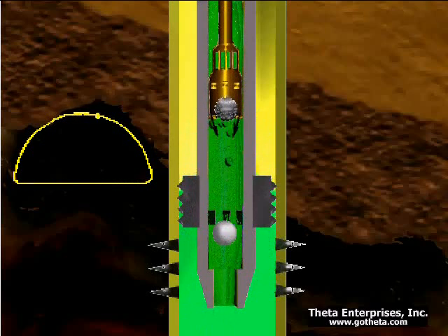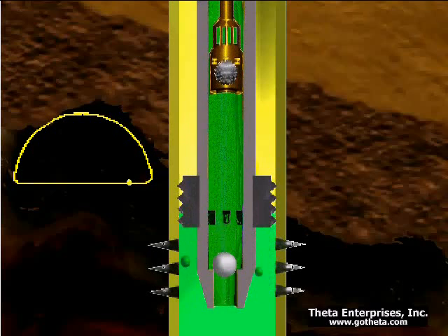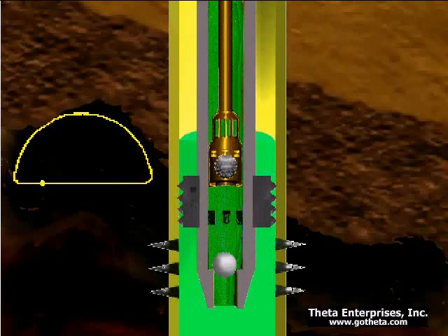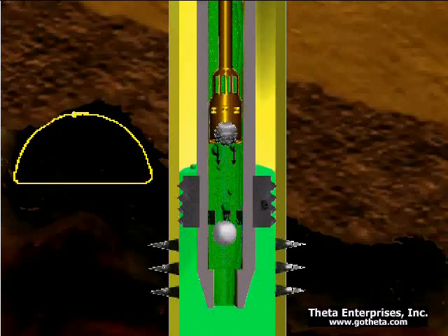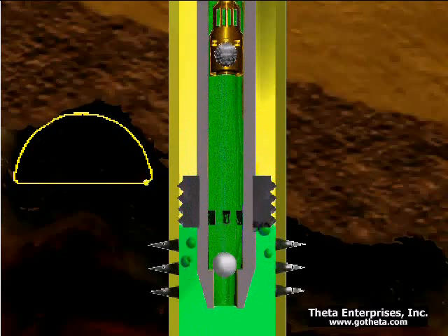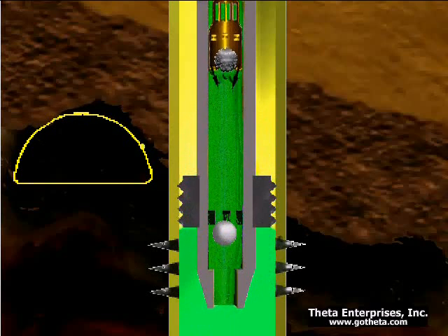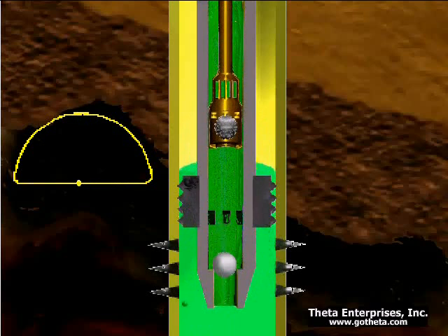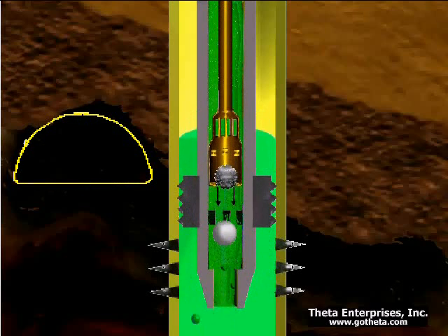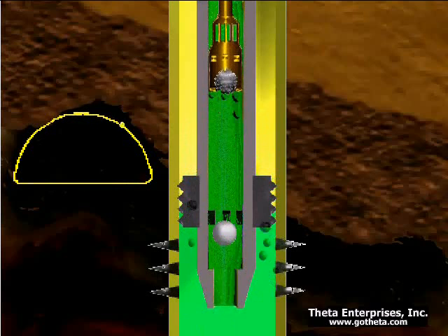But as the plunger goes past that point and it starts to slow down, then it's going to start losing load here. Of course, on the downstroke, having a worn ball or seat doesn't affect the loads because the loads are now on the standing valve. So this only affects the top of the stroke, the top of the pump shape.